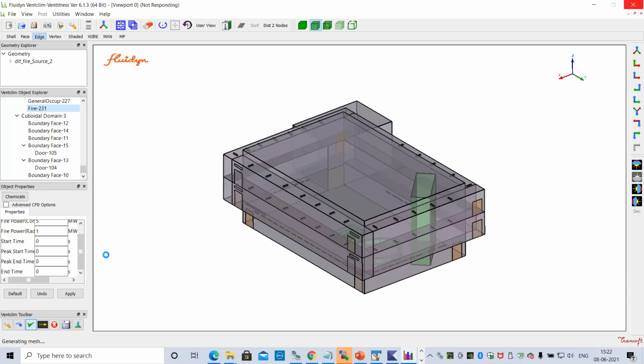Based upon this, once the mesh is generated, it will display the mesh over the geometry. If you do a few cases and grid independence studies, we come to know what the typical mesh is that we have to use. Suppose you don't know, you can use the default mesh. From there, if you want to refine or coarsen it depending upon your need, the grid fineness and other factors can be changed.